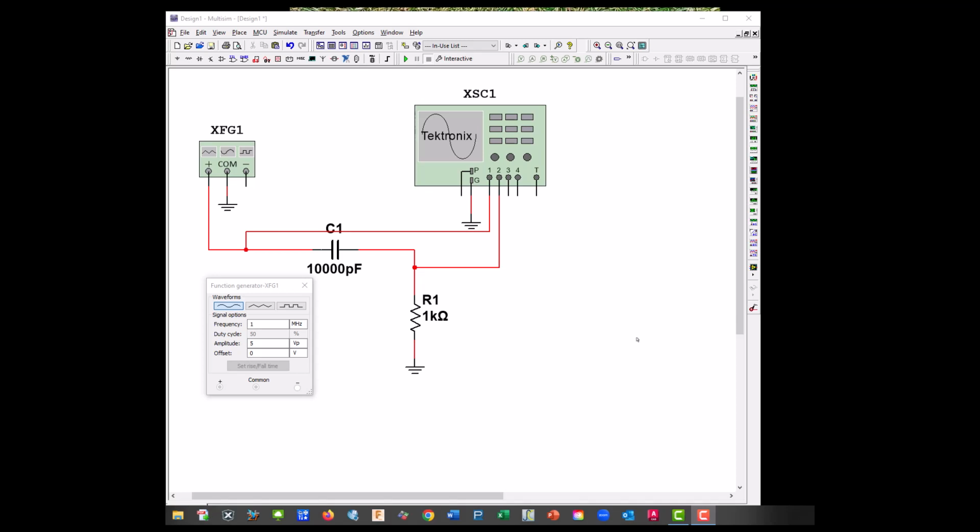The first thing is the old school way to measure the cutoff frequency. Cutoff frequency is the way that the filters are rated, and the cutoff frequency equals 3 dB down, or loss. So it is 0.707 times the input voltage. It shows where the cutoff frequency is. I'll show you a Bode plot in a bit, which shows the characteristics of this filter.